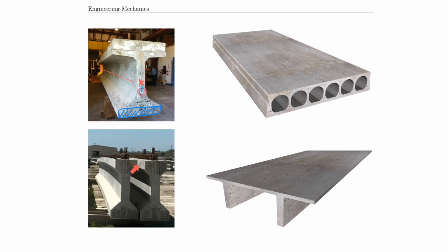Similar down here, this is, like I said, the AASHTO girder. And the AASHTO girder has the same idea, right? So there's a lot of material here, bulky on the top and on the bottom, but nothing in the middle. And this one would maybe even be easier to convert into a rectangle, but then we would have a lot of material here, and that would not be conducive towards carrying the loads. So let me just bring that home, also at the centroid location here, so that you understand that the material is far away from the centroid location.